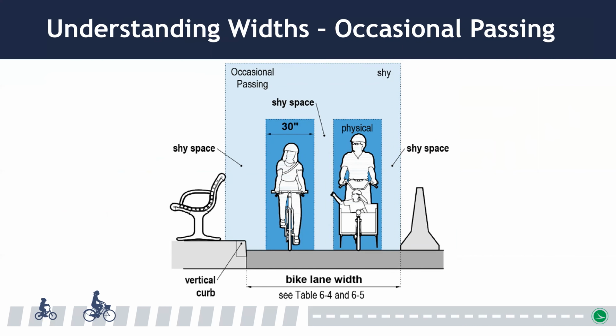On a constrained bikeway width, riders must generally operate single file and can only occasionally pass a slower bicyclist. During a passing maneuver, there is a higher crash potential between these bicyclists because of the limited operating space provided. Narrow bikeways therefore force single file operation or slow speed passing, which precludes opportunities for social cycling.